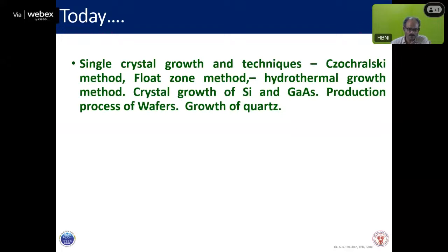Today, what we are going to learn is single crystal growth and growth techniques. Some of the techniques like Czochralski, float zone, hydrothermal. And then we will also see how the crystals of silicon and gallium arsenide are grown, and then how to make wafers out of these crystals. And another important crystal is quartz. We will see how the crystals of quartz are grown.